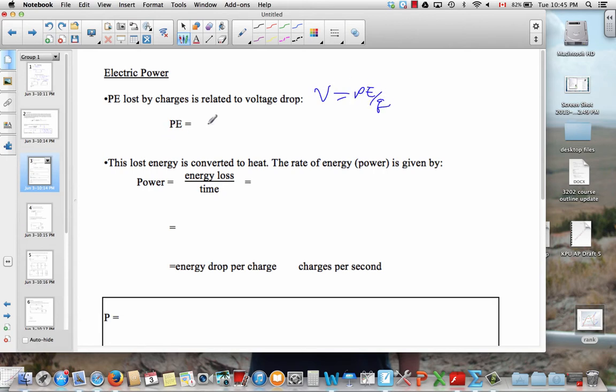Now, we said that voltage is the energy per charge. So that means the energy can be found for a given charge if you know its voltage. Now, as current flows through resistors, the voltage is lost and transformed into, say, heat and or work, and power is the rate at which that energy is transformed. So an energy is a charge times a voltage, and we divide by time, that's a power. Then we can group that, that's going to be voltage times Q over T.